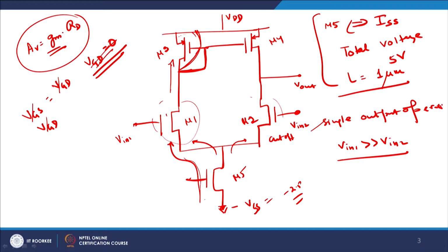See, here your source and drain voltage and your gate voltage are equal. So, Vg and Vd are equal. If you put source here, Vds and Vgs are always equal.